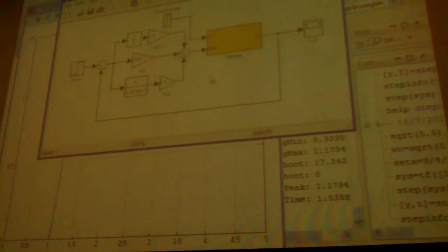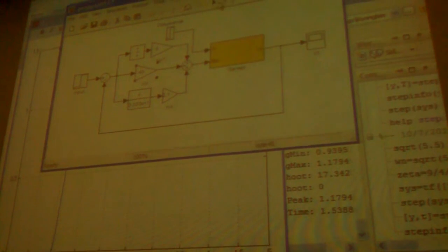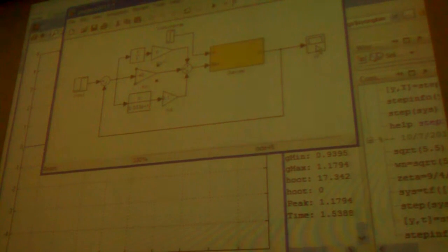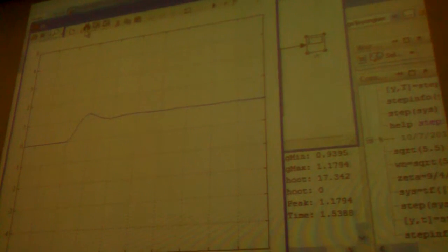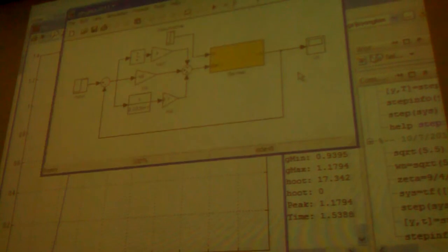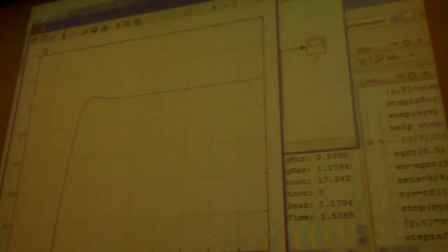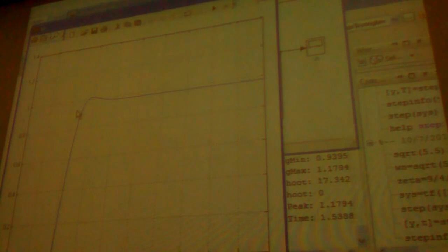So I'm going to increase the gain; the reference is 40, so I'm going to make it 40 first. Run again, let's see the response. It's about 20%. So I'm going to increase it, and you said 5? Let's start with 5. If you run this, yes, 5 is working fine. 10 is a graceful way to do it, but 5 works fine.